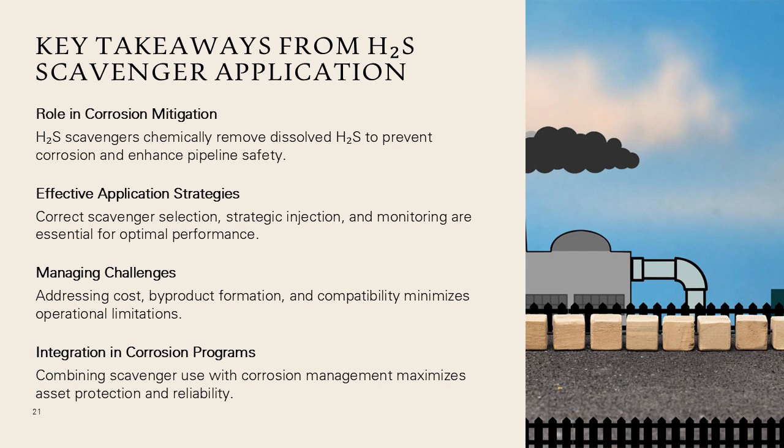H₂S scavengers play a crucial role in mitigating corrosion and improving operational safety in oil and gas pipelines. By chemically removing dissolved H₂S, scavengers disrupt corrosive mechanisms and reduce risks of equipment failure. Their effectiveness depends on correct selection, strategic injection, and continuous monitoring.